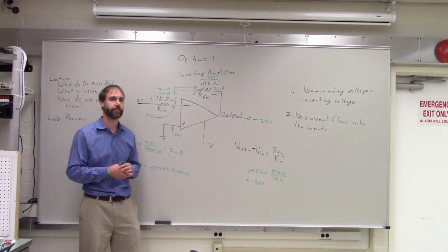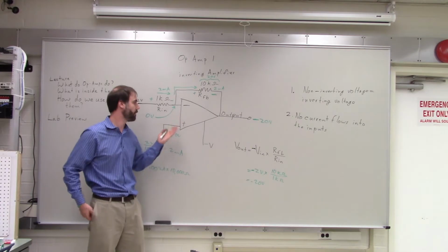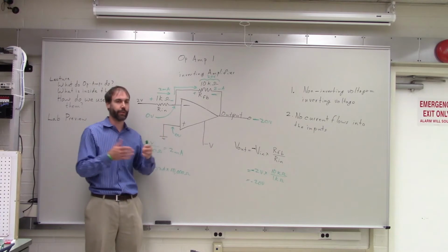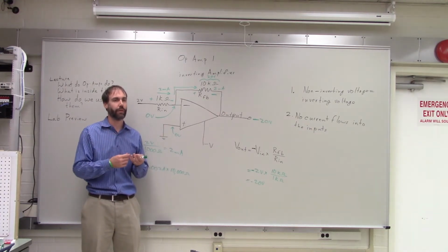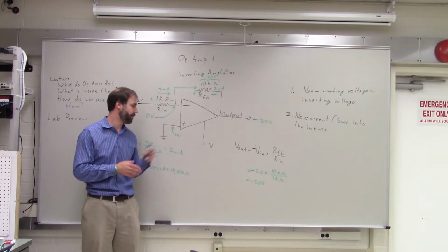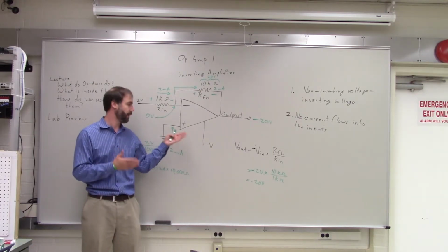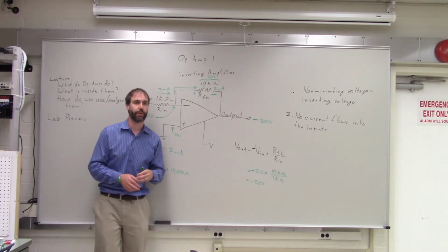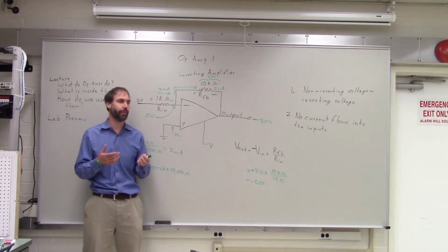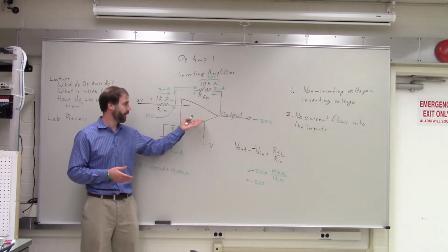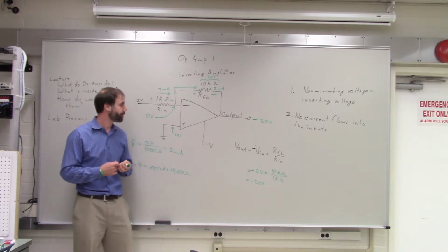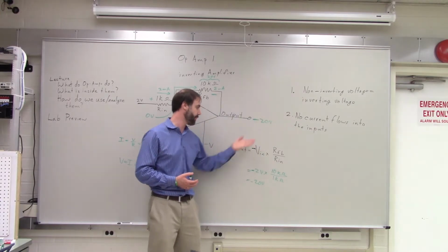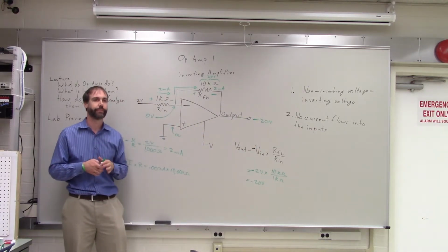Is that because of the diodes inside, right? Yeah, it's because of the internal circuitry. I don't know enough to say exactly which components they are. Sorry, the transistors inside. Right. Because of the way that the internal components are set up, the output can't go quite all the way to the supply voltages. So again, depending on which application you're building, you can choose a chip that meets your needs. And as long as it calls itself an op-amp, you can still analyze it using these rules and these formulas that we're learning today.